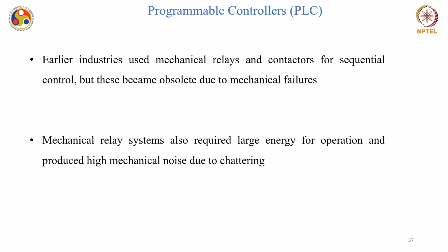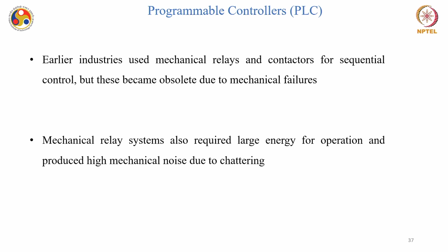Okay, earlier industries used mechanical relays and contactors for sequential control, but these became obsolete due to mechanical failures. And also in a practical sense, even for a small change, I cannot change all the relay configuration, or do rewiring where thousands of relays are working together. Okay, so a simple program has taken over that. Mechanical relay systems also require large energy for operation and produce high mechanical noise due to chattering. It also requires a lot of space to accommodate all these relays.